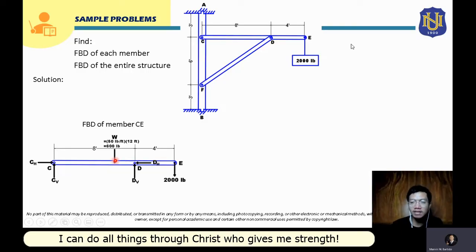After that, our step 3, we have to show the reaction forces that are provided by the support. So again, we will start providing the reaction forces to the support, where we can assume the direction properly based on the given load. Here, the load is 200 pounds.